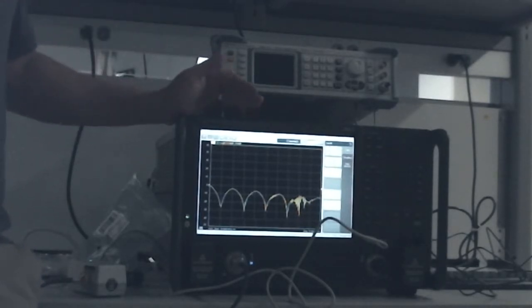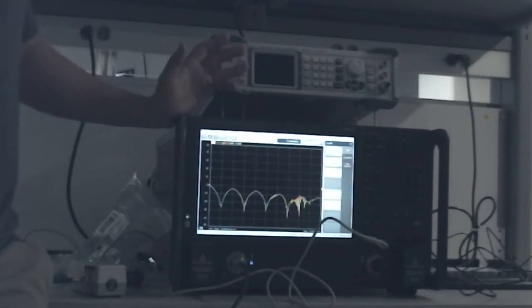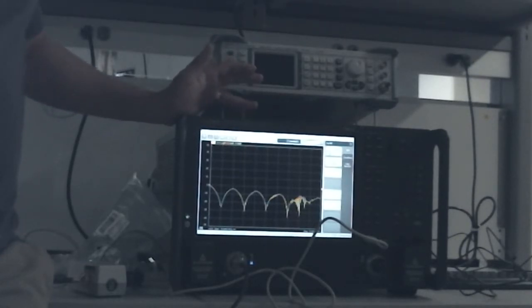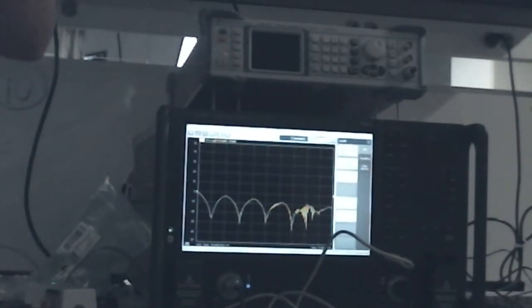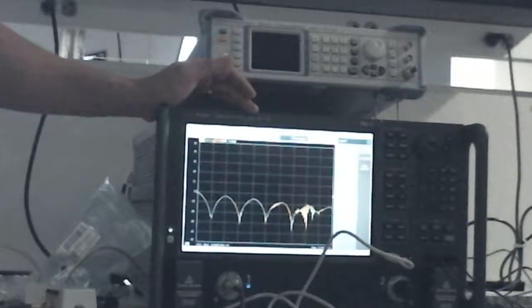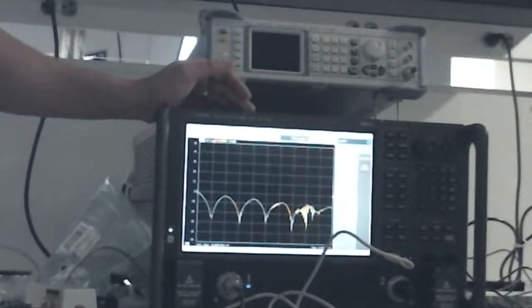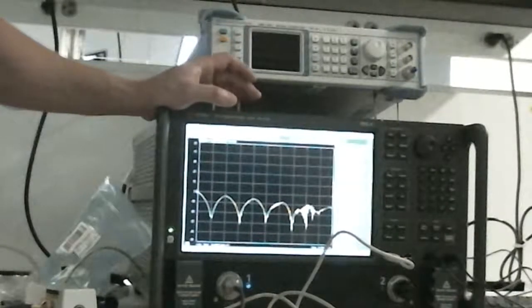And because you're only looking at the linear response, you know automatically at what frequency you're going to be receiving your signal, right? Because it's a linear device. So what you're doing there is that you can then digitally filter the signal at the output and allow for a much better signal-to-noise ratio, right? That's how you get the really good high dynamic range that's inherent in a network analyzer, is by being able to access a very narrow IF bandwidth.